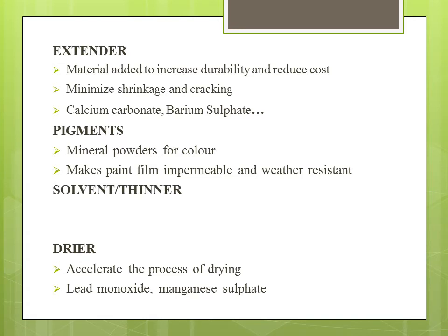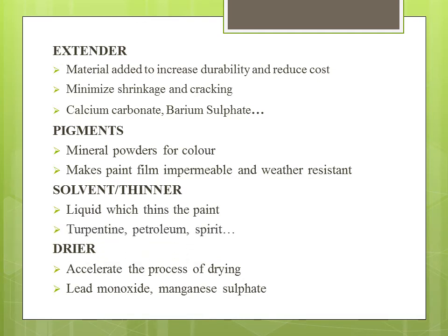Moving on to the next component, solvent or thinner. It is a liquid which thins the paint. Usually used solvents are turpentine, petroleum, spirit, etc. And the last ingredient is dryer. It accelerates the process of drying. Lead monoxide, manganese sulfate, etc. are commonly used dryers.